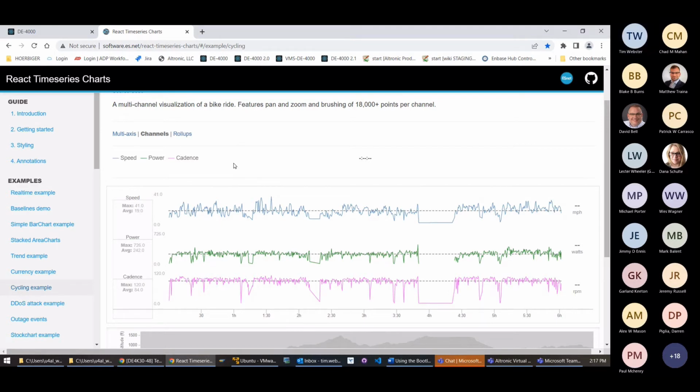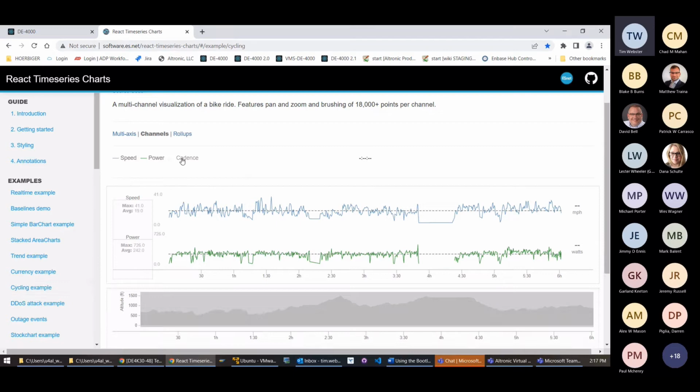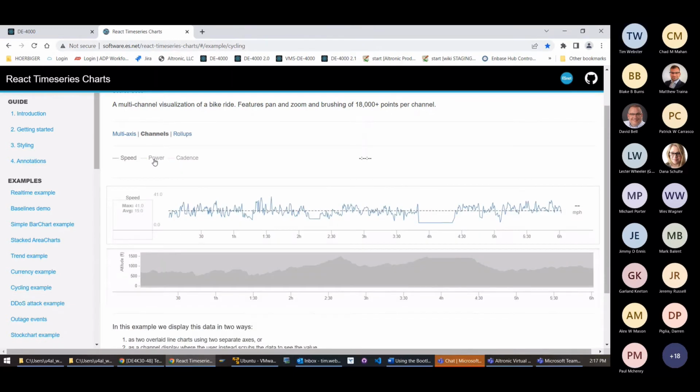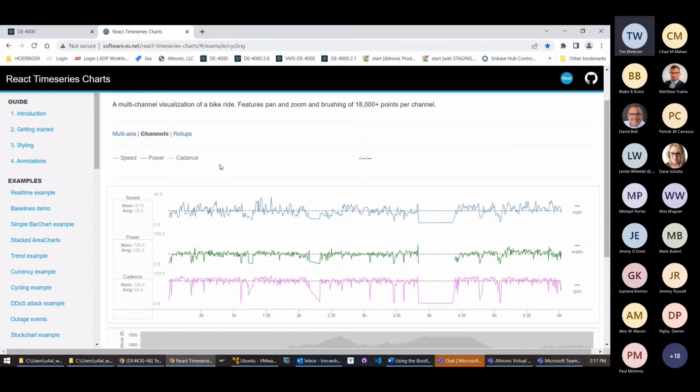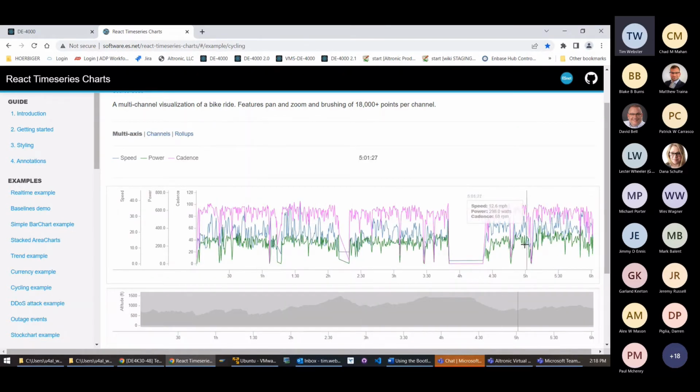And just with a simple click of a button, we can go to different types of graphs within the one graph. So here we've got 3 channels. We can turn on or off individual channels. And so for our system, when you start at the channels, you've got that one graph. You hit the button, it will bring you into the trends still with that one channel, and then we'll have an add button where you can start adding additional channels onto that graph and look at them side by side. So you can do side by side like this, and then we can also do a merged graph.